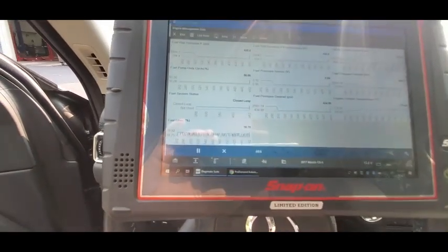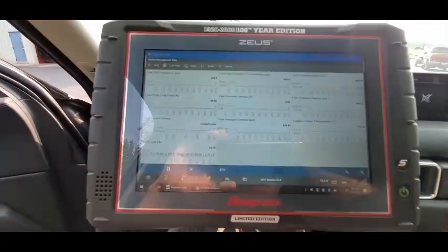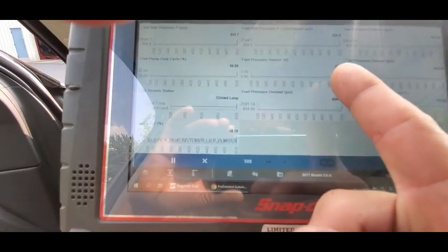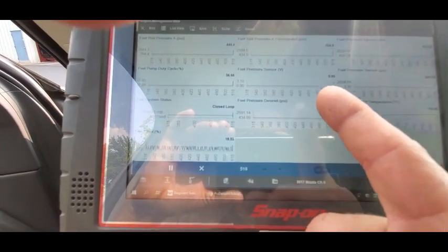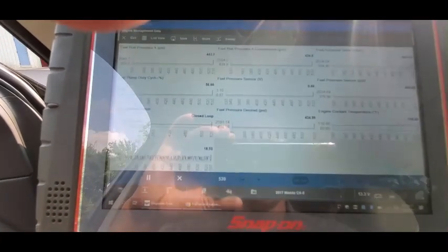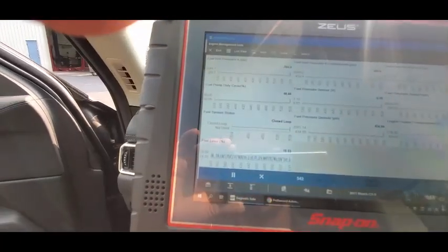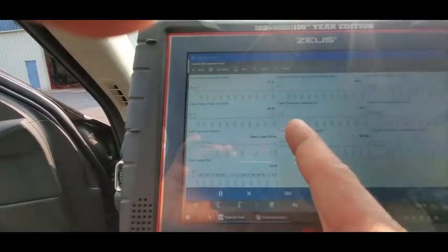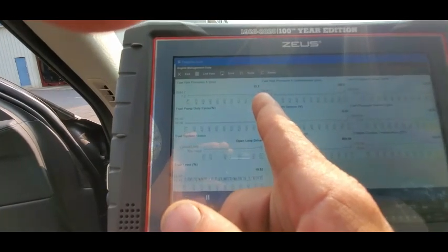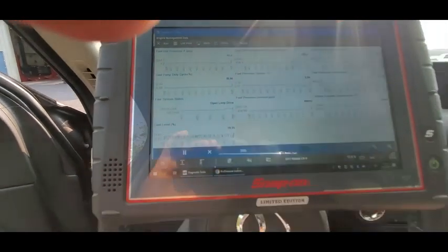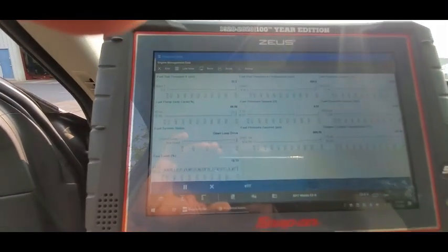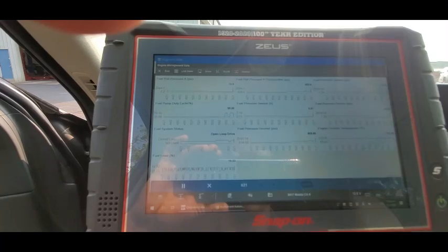So it died on the road. So now the question is, circuit low on our pressure sensor, if this pressure sensor circuit drives low, what's the effect going to be? Oh, there she just died. Look at that. 33 PSI. We might have a low pump problem. Oh, there's that long, now it definitely, yeah, long crank time.